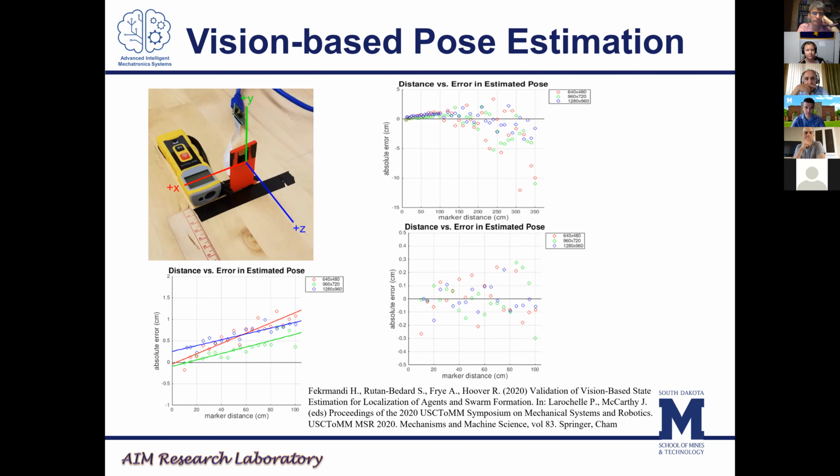We can see the low resolution cameras are getting relatively inaccurate at ±10 centimeters. But then if we cut that distance down to just 0 to 1 meter, we can see the error is quite linear for all of these different cameras. So we can just subtract off that linear offset, which might be just imperfect calibration or the tag size not being 100% perfect. Then we can get the error at 1 meter distance down to about ½ centimeter, which is really accurate.